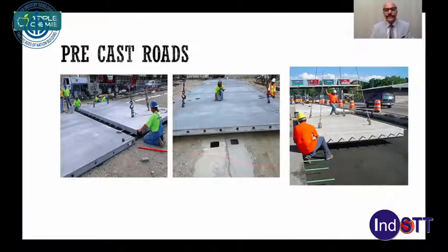That is why, what you can see in the center of the screen, there are shims on the road, which is a leveling mark to what extent the fill can be done. And to your right, you can see the shims are fully embedded, and the stone dust or any other subgrade is put flush with that. Now, as you have got a leveled base, you can put your panel on there. If there is a little bit of a deviation in this, then you will find cracks, and then there are a lot of challenges in the road segment.